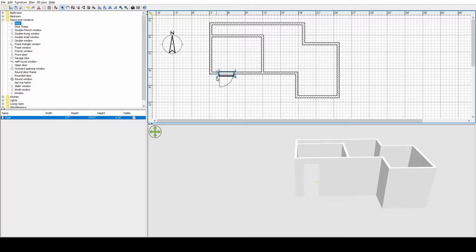You have to be very precise to bring the tool over here. That way you can adjust the height of the door, just drag this way and this way. This is another tool on the top corner, the elevation tool, so you can adjust the elevation, the placement of the door. From the bottom the space increases without changing the height of the door. This is especially useful for windows and things like that, not for doors. For doors you generally don't need to adjust this elevation point.